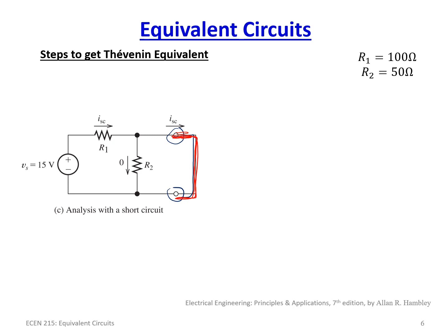And of course, we now have changed the dynamics of the circuit. What we're going to use to determine this Thevenin resistance is ISC. We're going to determine what is the current going through this short circuit. So we've reconfigured our circuit, and we drew it this way. And now we're going to do an analysis on it and solve for ISC.